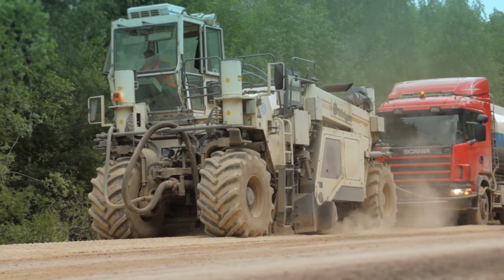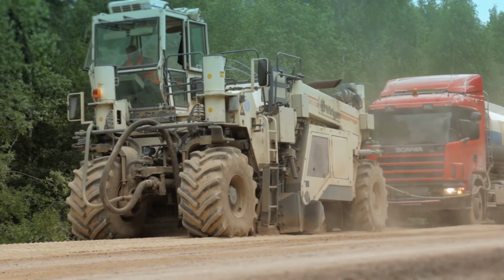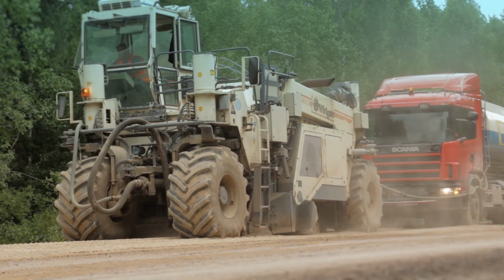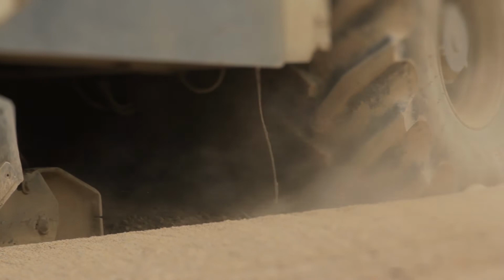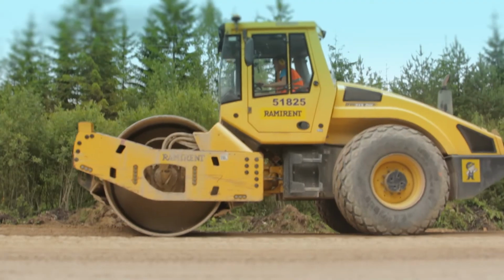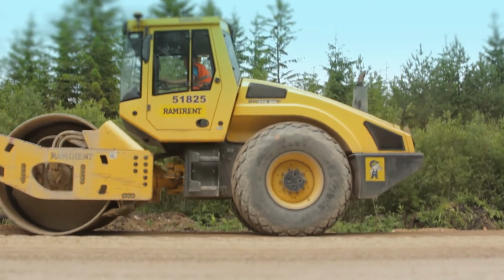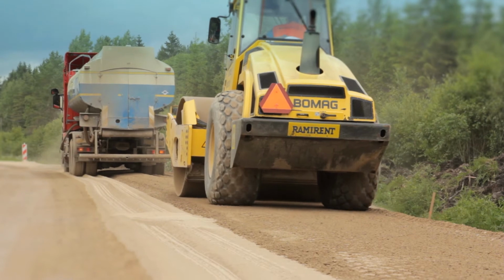The binding substance mixture was then laid by tractors which were specially adjusted for the purpose and allowed for the added quantities to be exactly controlled, so that the required amount of oil shale ash per square meter would be guaranteed. The stabilized layer was instantly compressed with a vibro roller. Timing was an important factor here. Compression had to be done within 1 hour of stabilization.